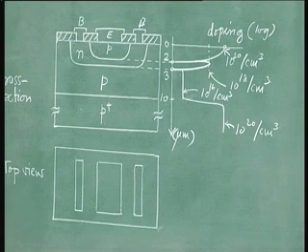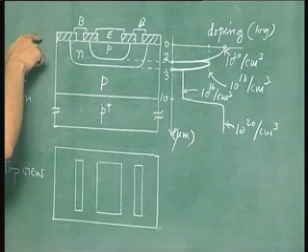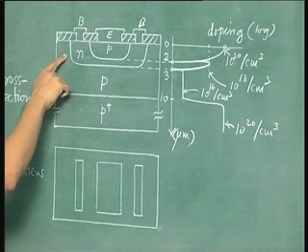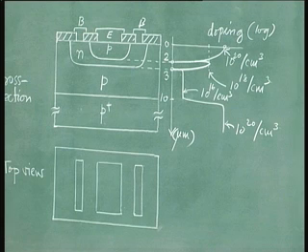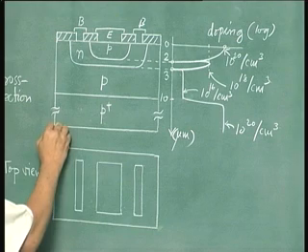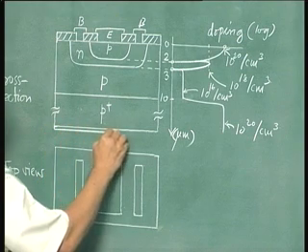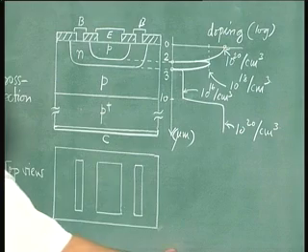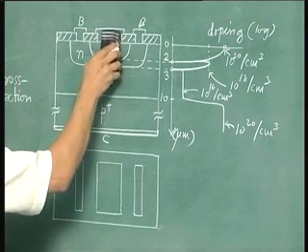What we are considering here is a discrete transistor. In an integrated circuit transistor, on the other hand, the collector contact will also be on the top, somewhere here for this particular region. For a discrete transistor, it is at the bottom. We will consider the discrete transistor here because its structure is simpler. So you have that contact at the bottom. This is the collector. So let us draw this emitter here.